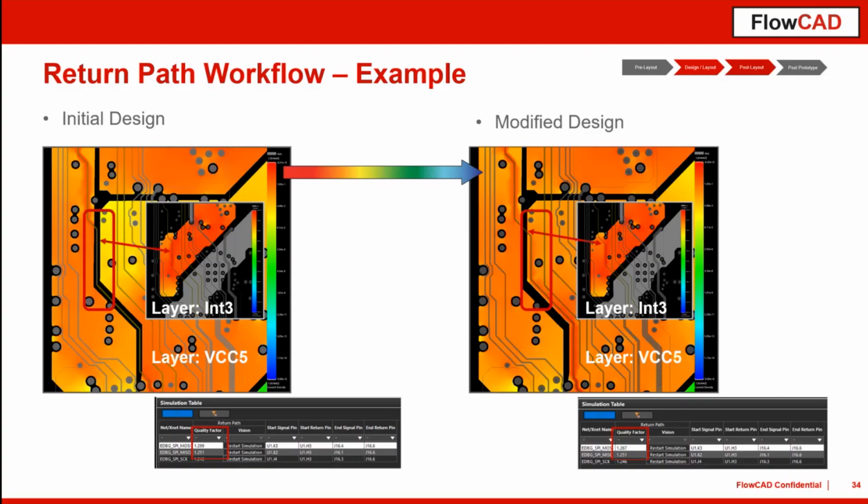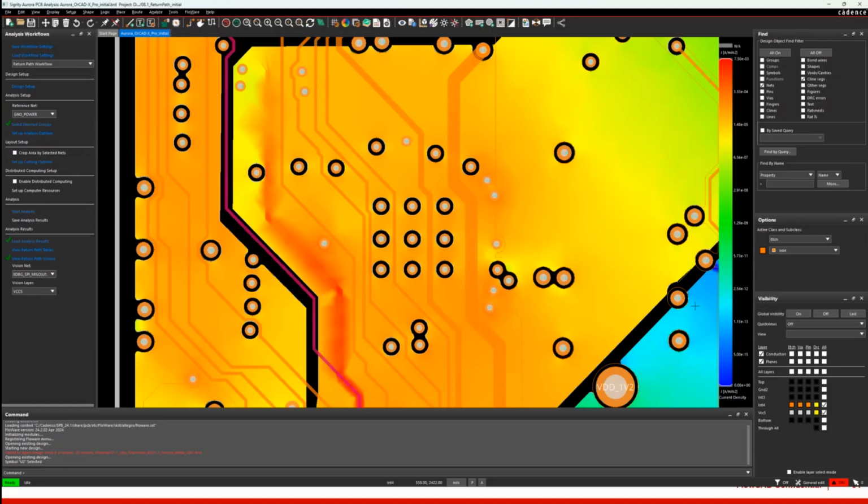So in principle, it can go through the complete design just to close the current loop. And in this case, it can collect a lot of noise from all other planes. But it can also create noise to the outside. And that is essentially the point where it makes sense to talk about why you should not route signals over such split planes. We can see this, I think I opened this in this design.